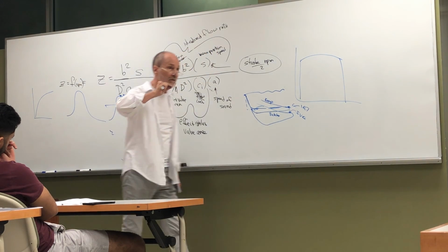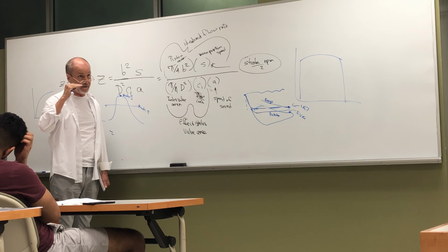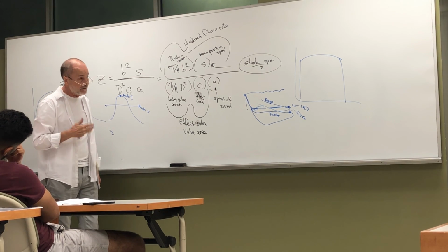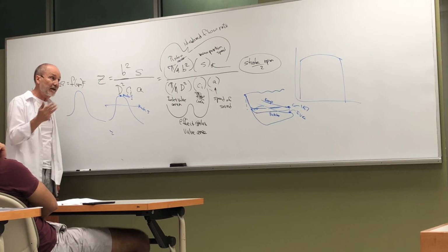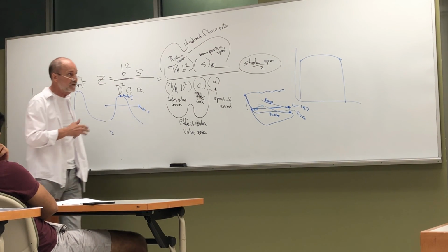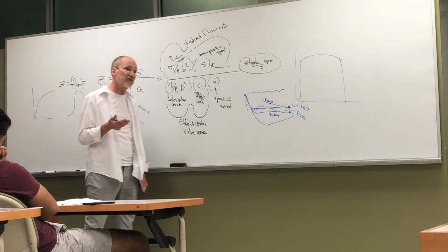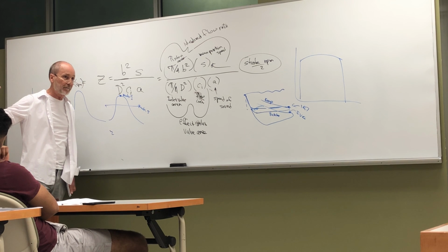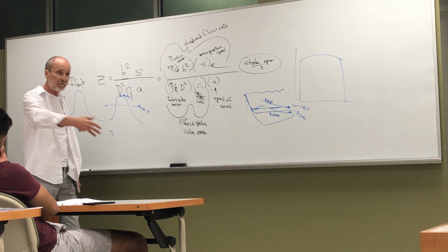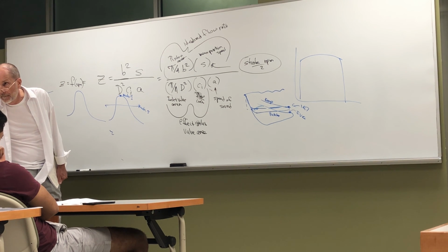So if you want less power, the camshaft doesn't open the valve as much. And there are other mechanisms that allow you to affect the duration. Variable cam timing, each manufacturer has come up with a way to do it. It's so beneficial, and you don't want to end up having to pay on patents to another company, so everybody develops their own.